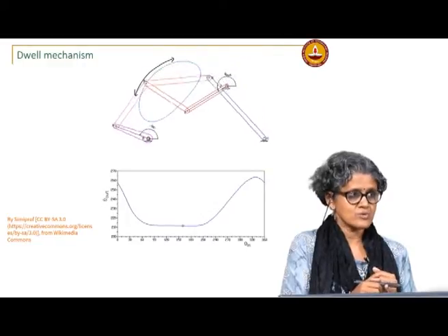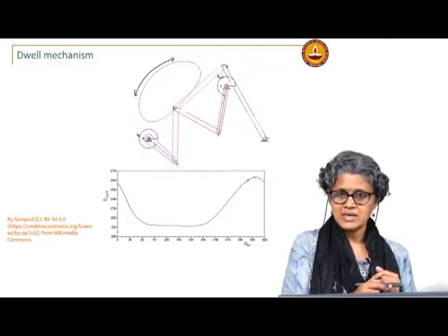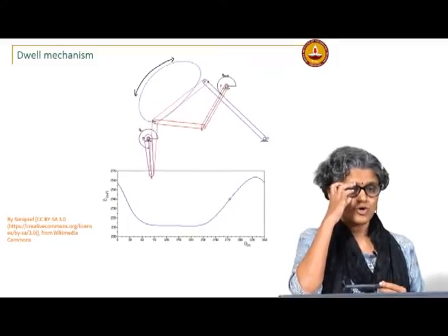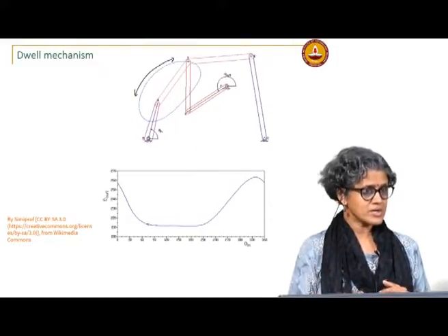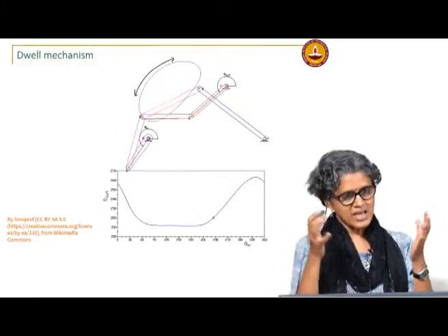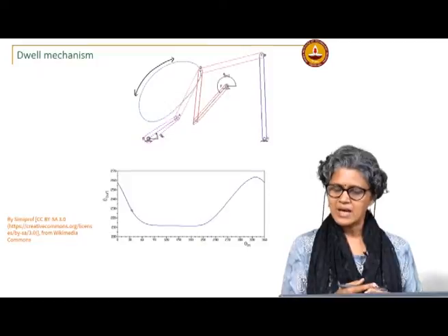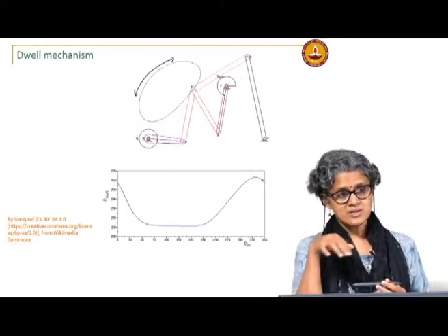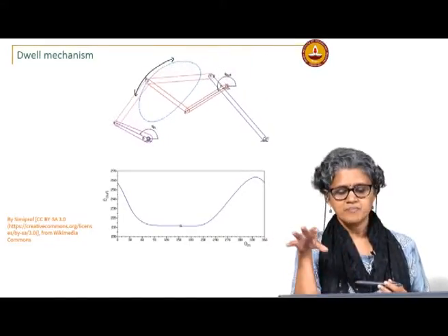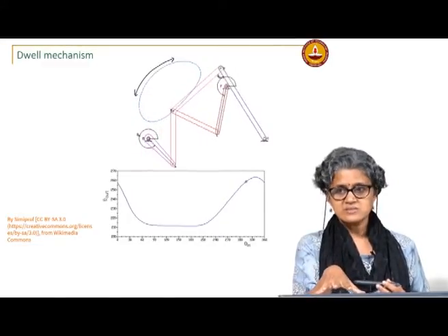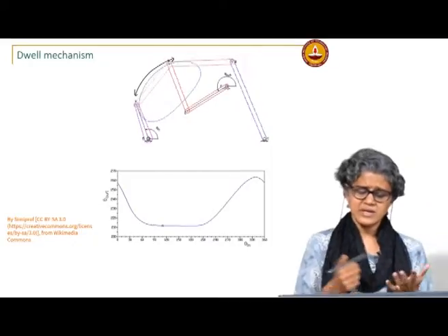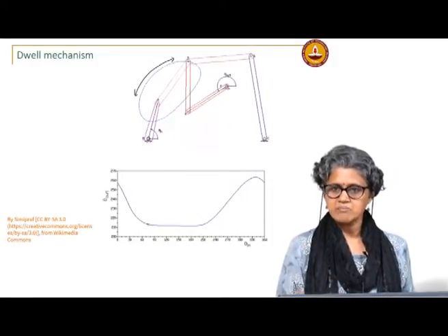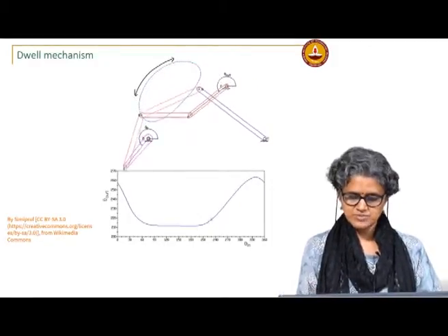So, wear can be high in cams, which of course changes your output for the mechanism. So, if you can do it with a pin jointed mechanism, then, of course, cams are more compact. So, it again depends on your application. That is really where the type synthesis that we first talked about comes in, because you have to consider a lot more factors when you are designing something. This will occupy a lot more space, obviously, a linkage, but if you can use it, then the coupler curve gives you a nice way of going about designing a dwell in the linkage.